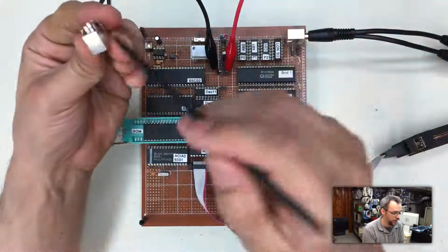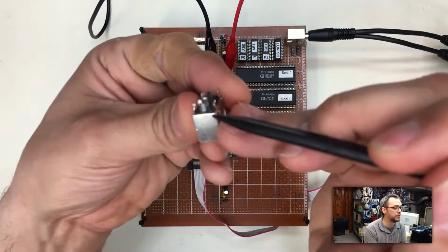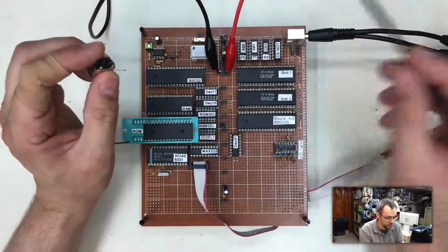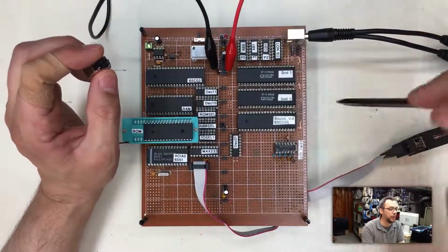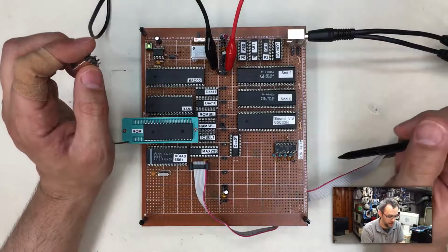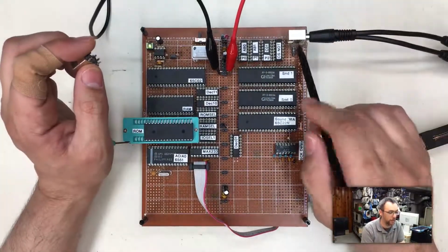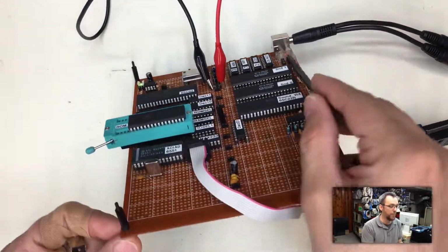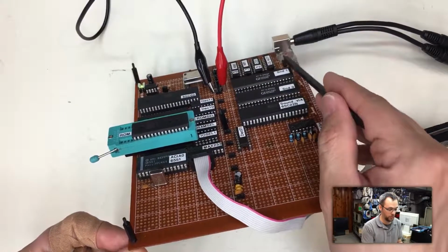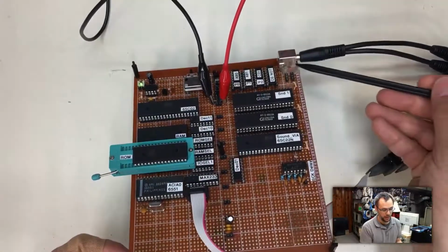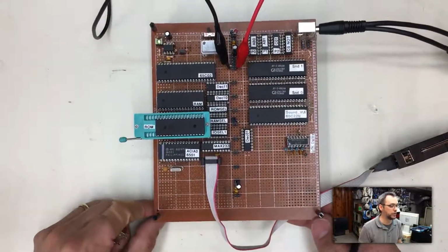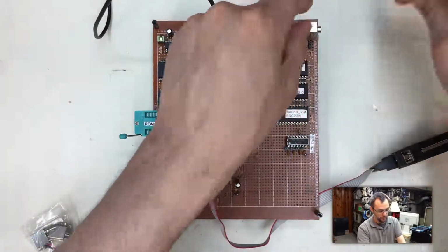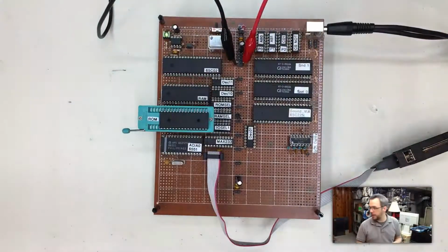Now the pin pitch and pin width of these sockets is too big and doesn't match my breadboard whatsoever. So I just tacked some wires on here, brought them down through the board and soldered them on the back side. Then to secure this a little better, I gooped it up with some hot glue. The red wire, which you may be able to peek down in there, is the right channel. The white one here is left. And up under here is the black connection, which is the signal ground. That makes it a little easier for me to plug things in and out of the computer.